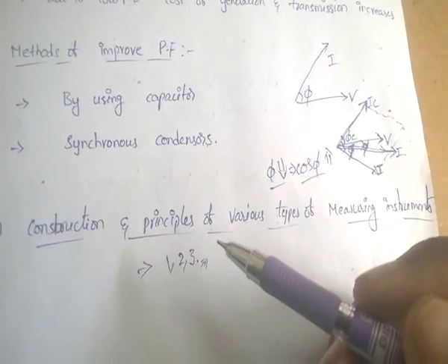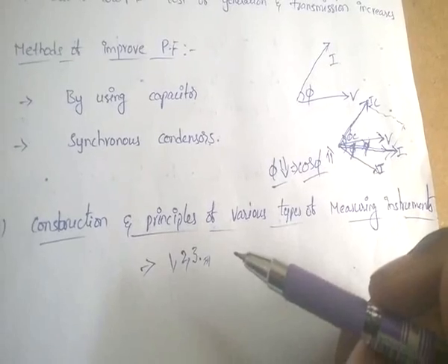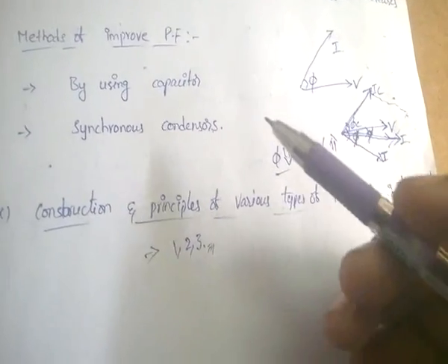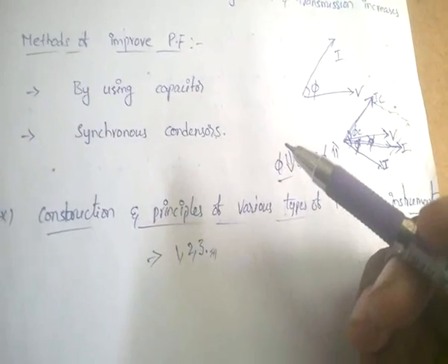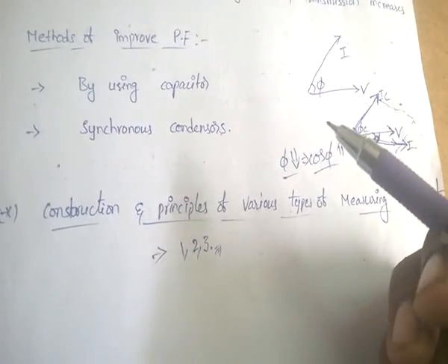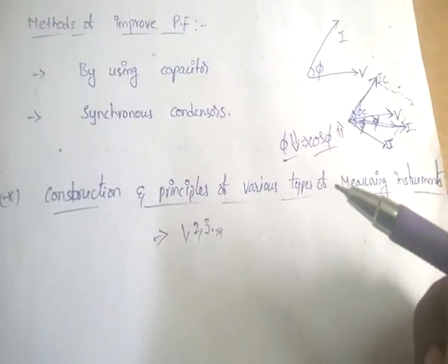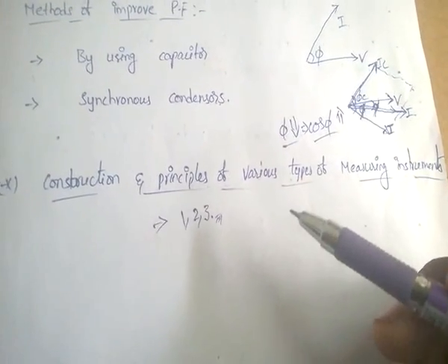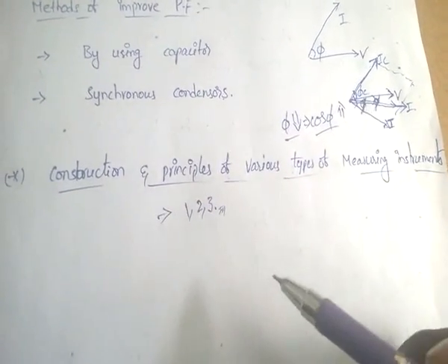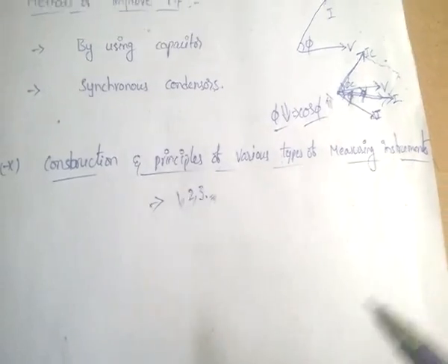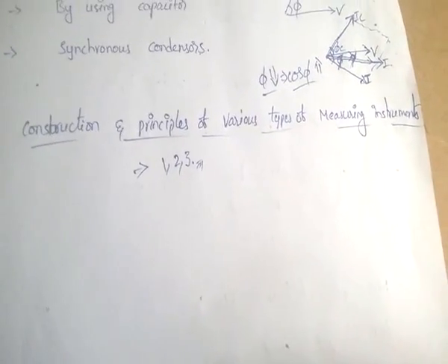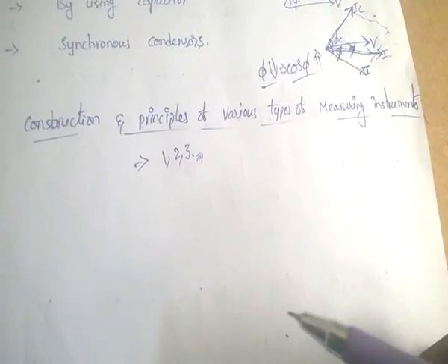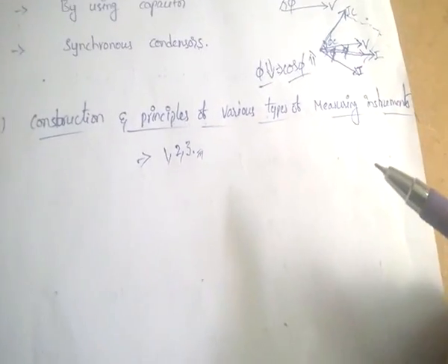First one, what is a phase voltage, what is a line voltage, or phase currents or line currents. Phase voltage is voltage between phase and neutral. Line voltage is voltage between two phases. Next, in case of star connection, line voltage VL equals root 3 V phase and I line equals I phase. In case of delta connection, IL equals root 3 I phase, VL equals V phase.